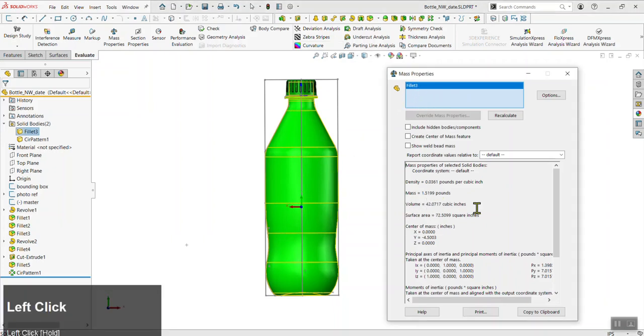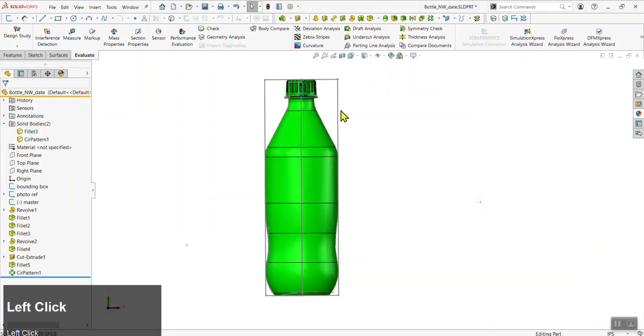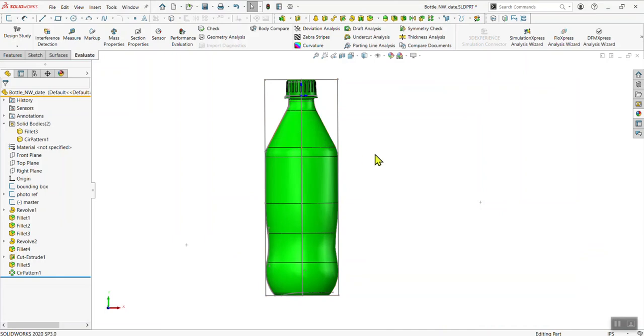Volume is important when designing packaged goods. Part of project one is setting up your file in such a way that you can get sort of a family of products. So you can get a smaller volume and a larger volume bottle. So now would be a good time to check this. Essentially what we want to do is modify the bounding box to make our bottle smaller and larger, and hopefully it rebuilds and proportionally looks the same.